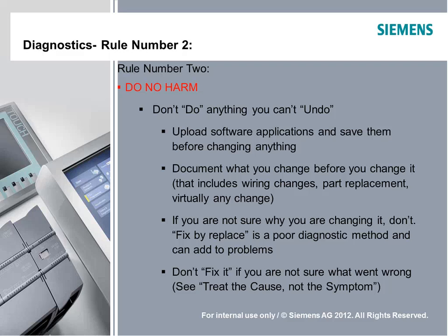So if you can document every step you take along a diagnostic repair procedure, everything from wiring changes to part replacements, any change that you make, just make sure you write it down, because in that situation you can oftentimes forget things that you did change. Another point here is if you're not sure why you're changing something, don't. Fixing by replacing things is really not a very good diagnostic tool.